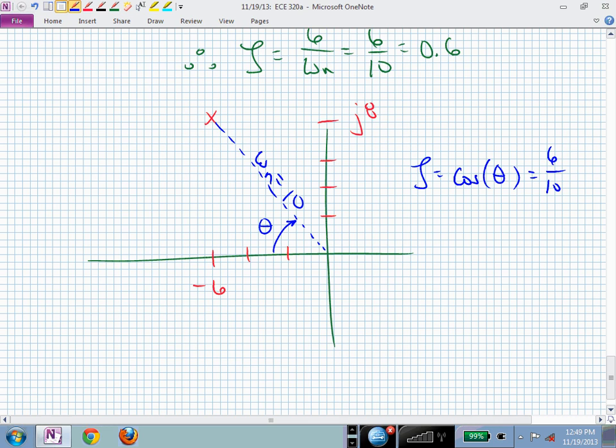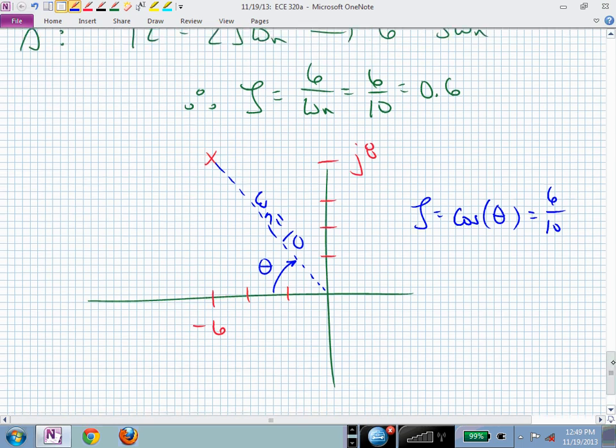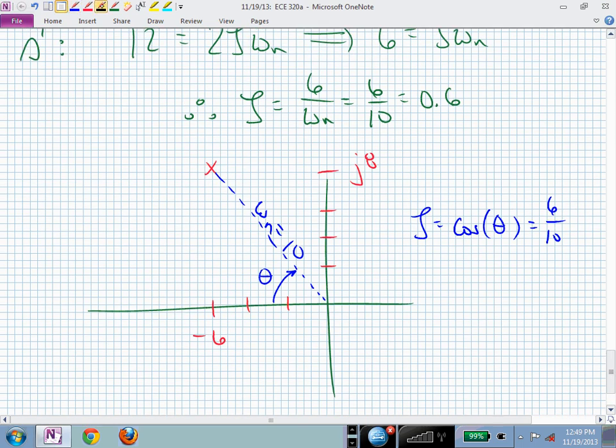What we're going to do in this class is make what you're going to think is a very large approximation. For this class, we're not going to worry so much about the damping ratio. We're just going to swing that pole that's at j8 and this pole at minus j8 around until they are completely real, and we're just going to sketch the Bode plot for those two real poles.